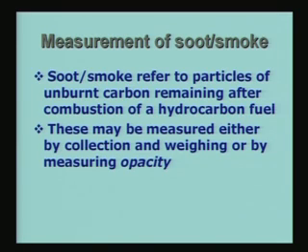So, in any combustion process, for example, if you take a diesel engine, the exhaust contains a lot of smoke, and you can very well see that it is because of the incomplete combustion of the hydrocarbon, and therefore, the unburnt carbon remains as particulate matter or particles, and these come out of the tailpipe of the car, if it is an automobile, or if it is a regular power plant, it will come through the stack.